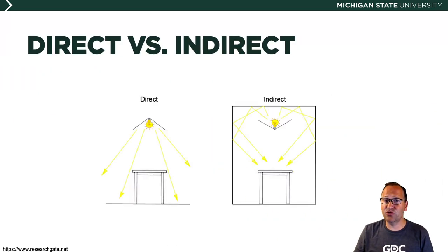Lights can be either direct or indirect. Direct light is light that is emitted, hits the surface once, and is then reflected directly into a sensor, such as the game camera. Indirect light is all other light that is ultimately reflected into the camera, including light that hits surfaces several times, and skylight. Unity can calculate direct lighting, indirect lighting, or both. The lighting techniques that Unity uses depends on how you configure your project.